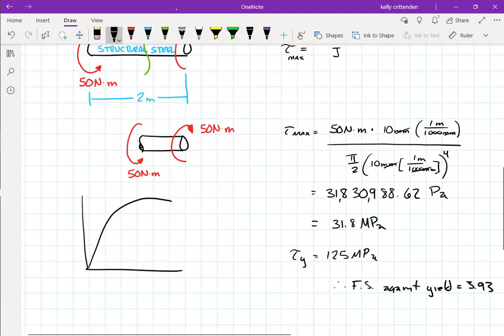There's a point somewhere where your slope is no longer linear, and so you enter a region where things don't behave the way that you originally thought they were going to behave. So if we had yielded the thing, then our equation that depended on that modulus of rigidity would no longer work. It would still give us a number, but it wouldn't be the right number. It'd be a way underestimate of what was going on.